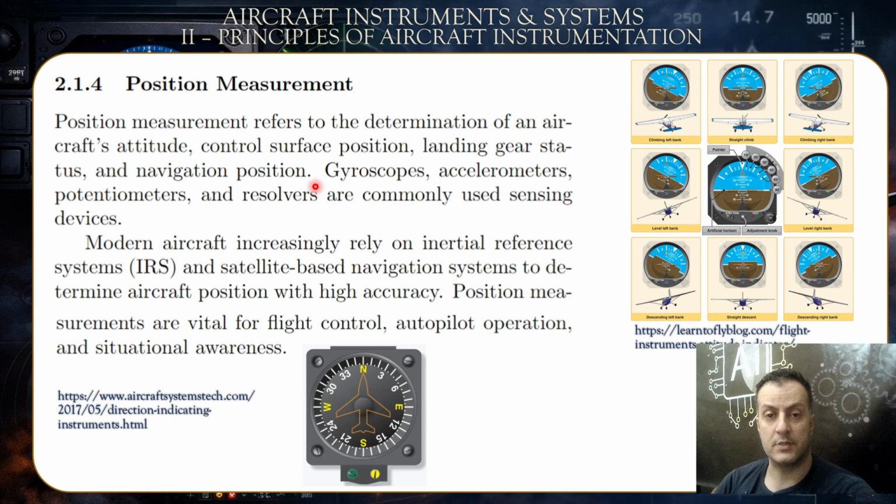The elevators would be measured, how many degrees, the flaps, so when you apply a flap of 5 degrees, you will see it changing on the display. The ailerons, etc. More than that, you have the attitude indicator, which again presents to you whether you're flying level. If the aircraft is pitched up, this orange line on top would go above, to the part of the blue circle.